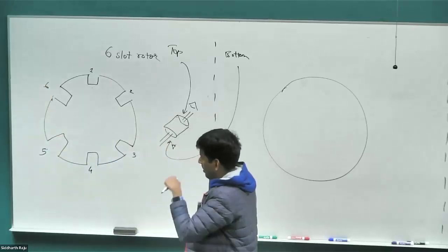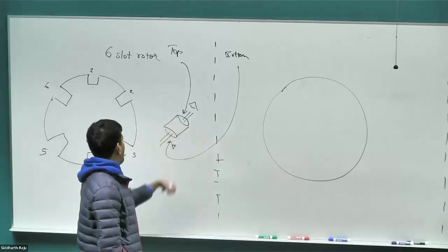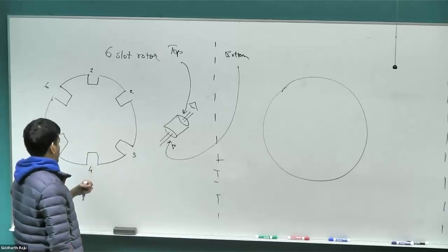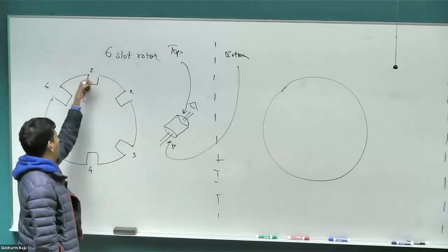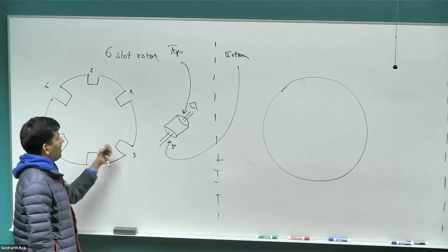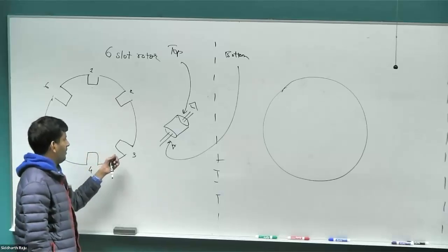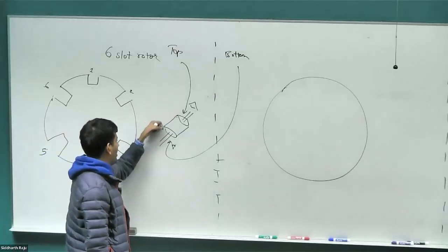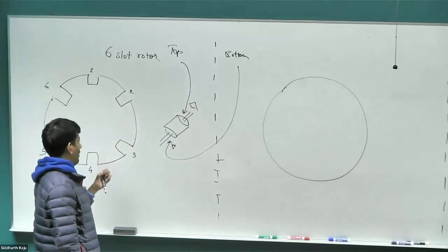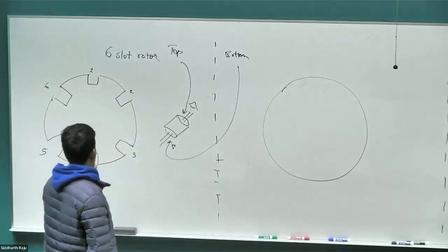The way they would manufacture this is to take a cylindrical block of iron, silicon steel, and then cut it into slices like you would a bread loaf. Then they stamp these holes into each of those individual rings that they have created, and put a varnish or some kind of lamination, typically varnish. Then they stack all of these together, weld at the edges or put some epoxy glue. Different things have different advantages and disadvantages regarding the stresses they create. And then through the middle, they'll put the rotor rod, and that's how they'll construct the rotor.